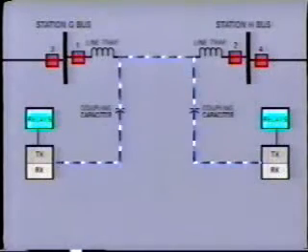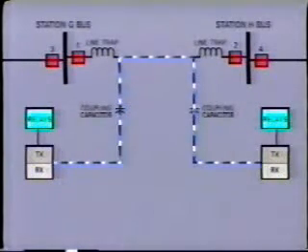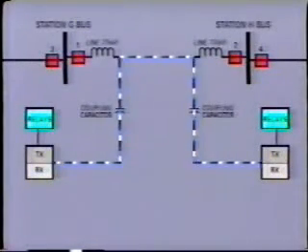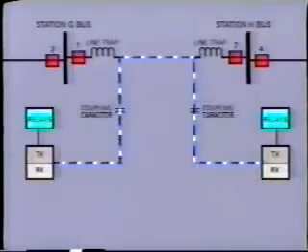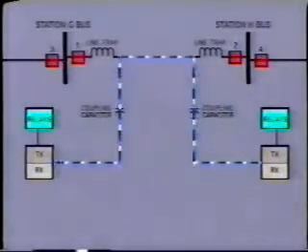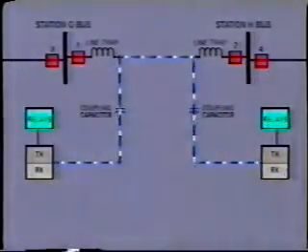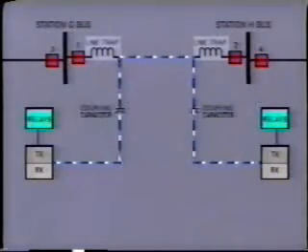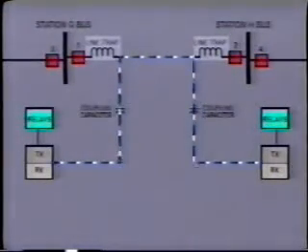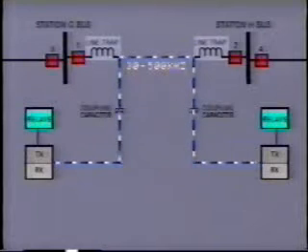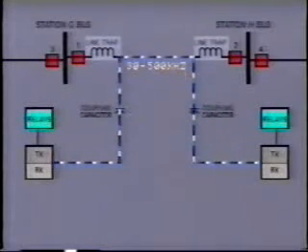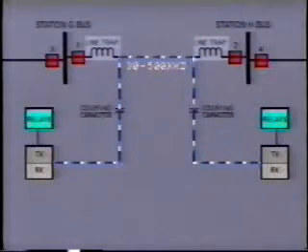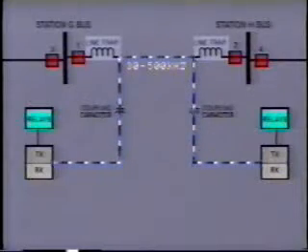As you already know, the objective of the line trap is to confine the injected carrier signal to the desired conducting path. That is, the transmission line between transmitter and receiver. The line trap or inductor is sized so as to provide a reasonably high impedance to the carrier signal, which may be transmitted within the frequency range of 30 kilohertz to 500 kilohertz.